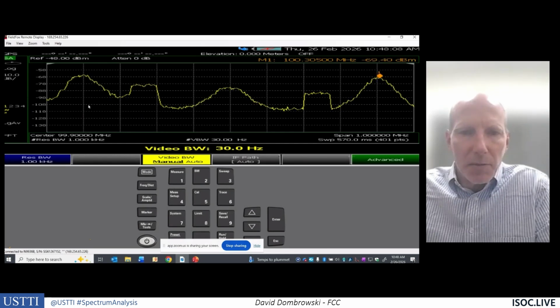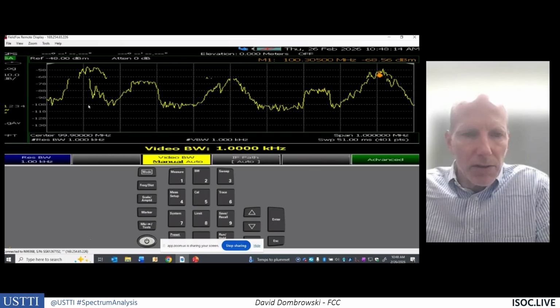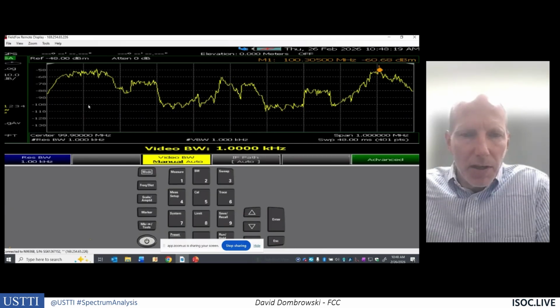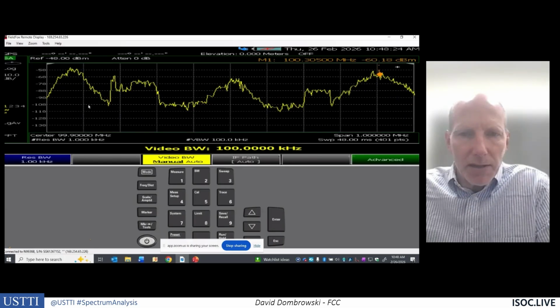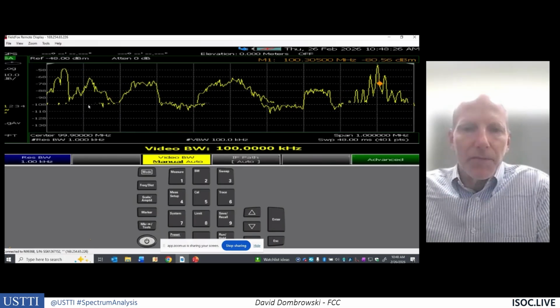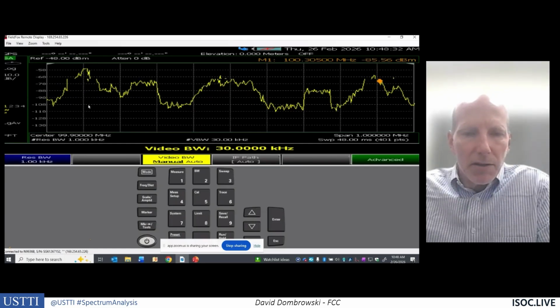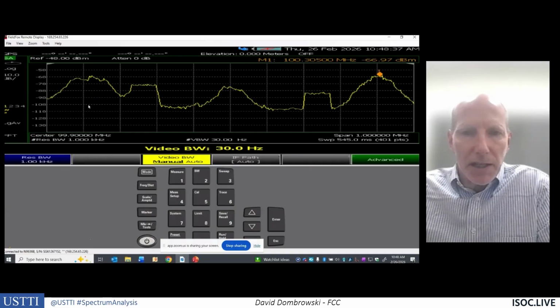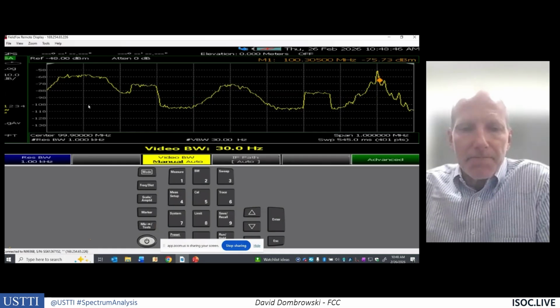And so we're not seeing all the frequency components. And so we like to keep it at 1 kilohertz or above. And you see you're not getting much change there, right? Once I keep it above the bandwidth of the resolution filter, we're not seeing much change in the display at all. So RBW is 1 kilohertz, and we're going to keep our video bandwidth at 1 kilohertz or higher. If we start to go below that, we start to get the averaging, which is bad for measurements, but good for looking for weak signals. I hope that answers the question.